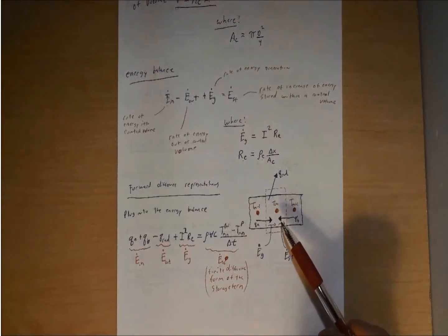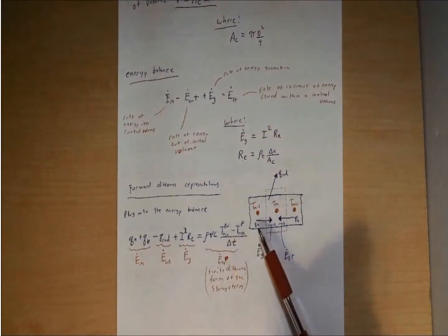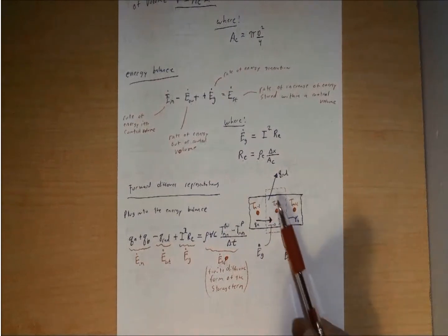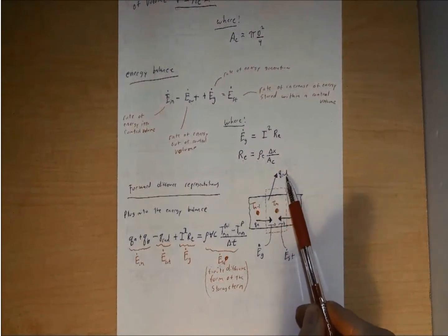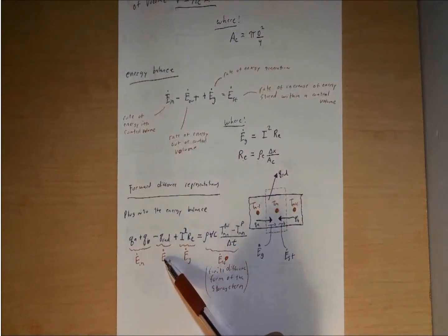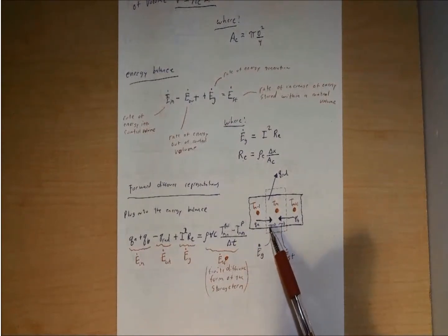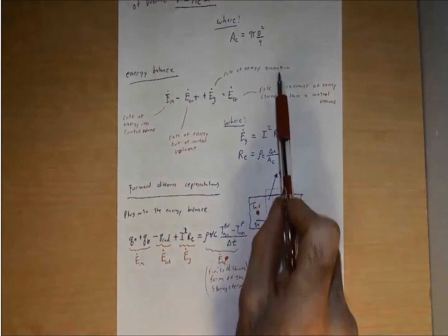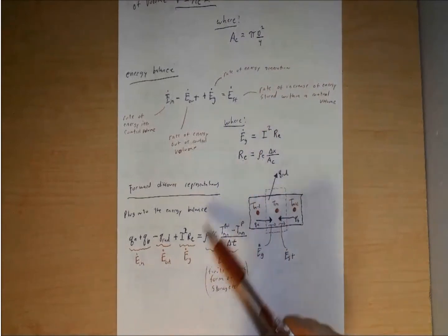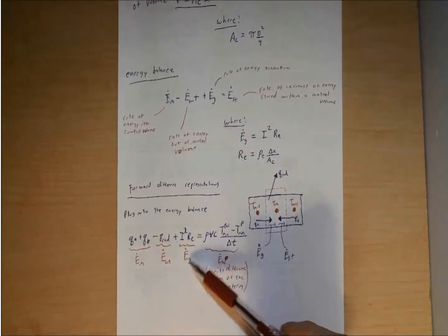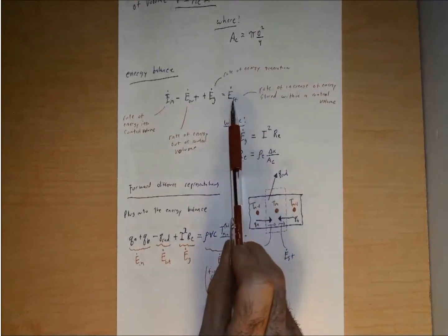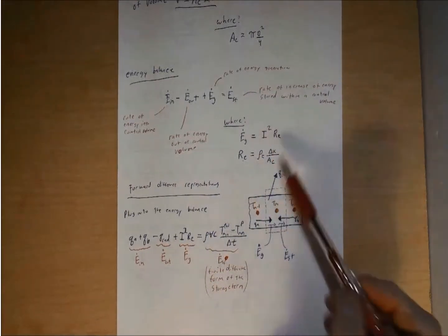So what we can see here, if we go back to our energy balance equation, what do we have going in? So going in, we have Q A, Q B. There's our Q A and Q B going in to node T sub m that we're interested in here. Now what's coming out is Q rad. So Q rad is coming out. And then we have our E sub G right here, which again is our rate of energy generation. And again, we have an equation for this here, so we can plug this in for our E sub G over here.